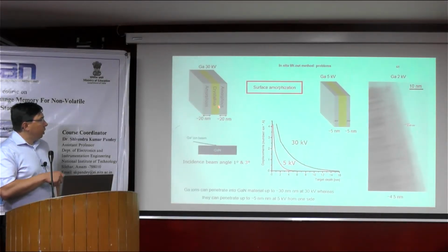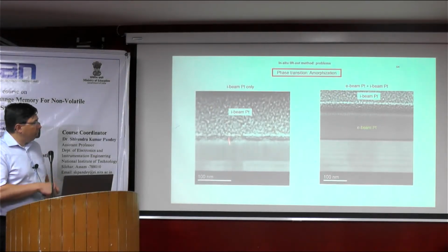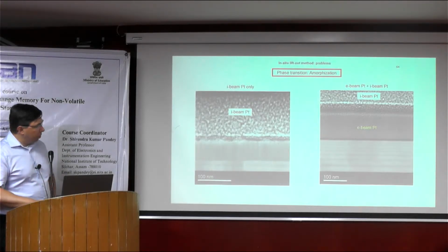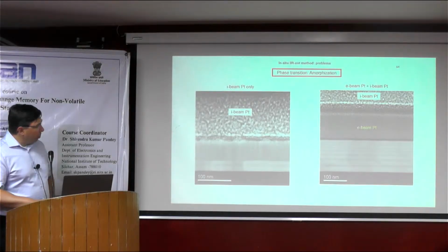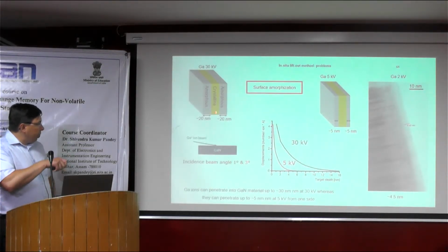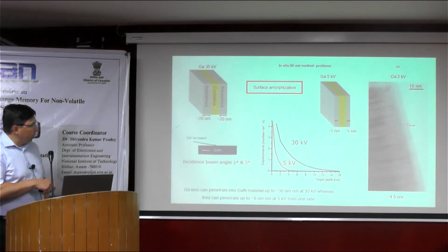Of course, if you use the ion beam pointing at 90 degrees to your sample, you can destroy it, like it's shown here. This is a very nice example. If you go directly, then even at 1 degree you destroy it. But if you go with 90 degrees here, then you will destroy your sample completely. So in FIB, you use incident angles like here, 1 to 3 degrees.